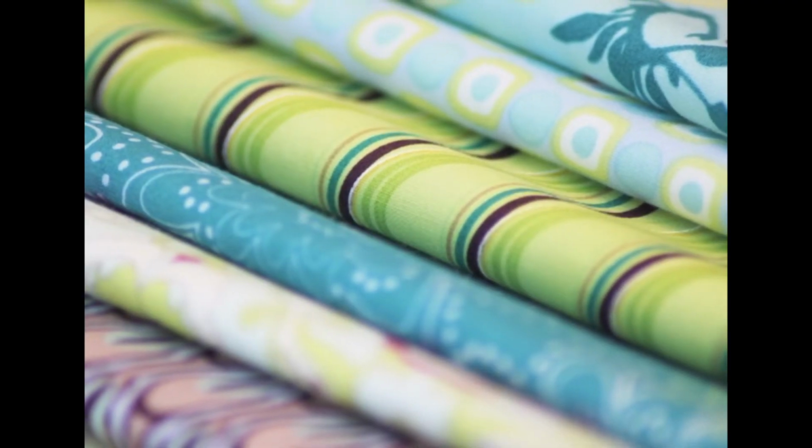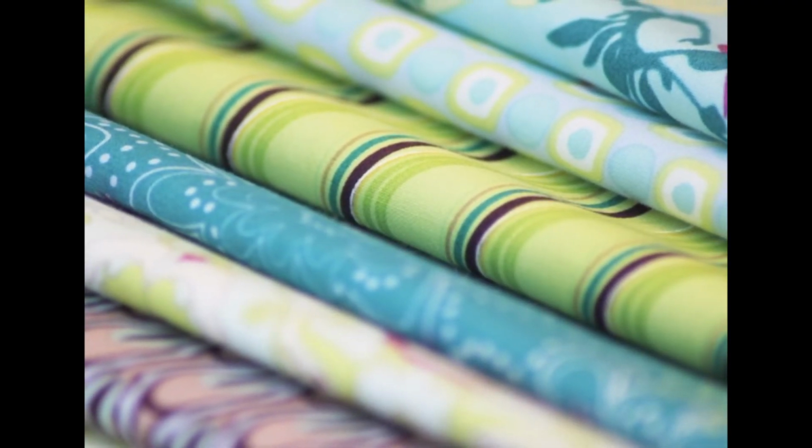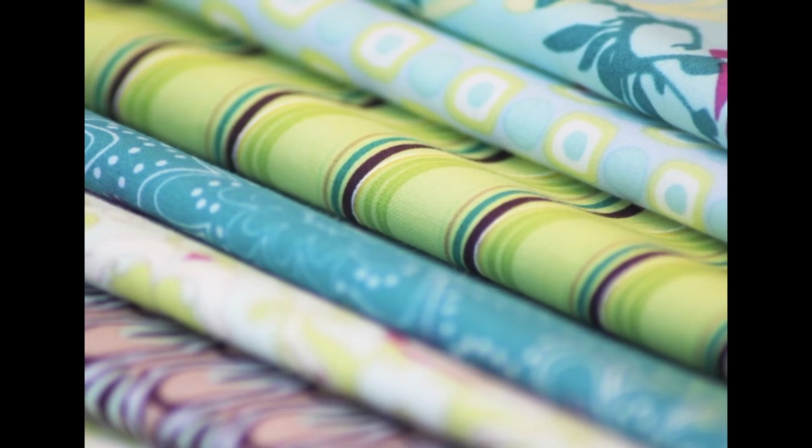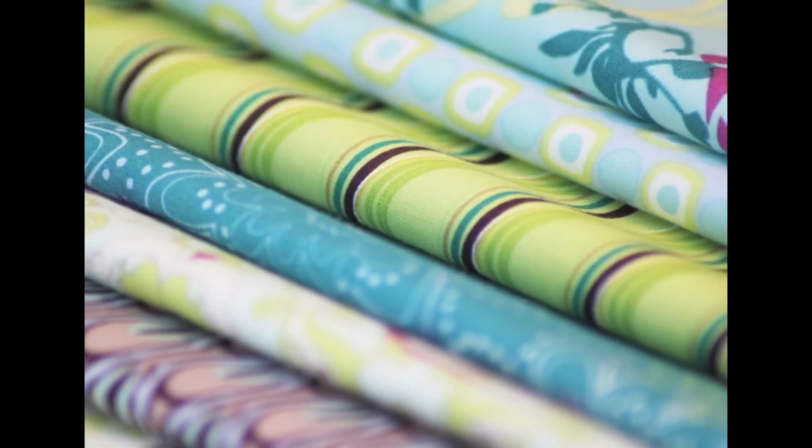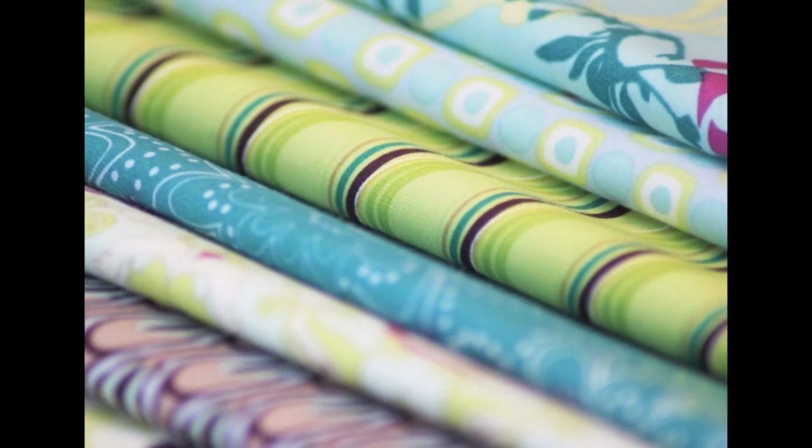Breaking strength of a fabric increases with the increase in fabric count, as there are more threads, and so the strength contributed by these yarns will be higher. However, tearing strength is decreased just because the threads are available for tearing one by one and not in the form of a group.